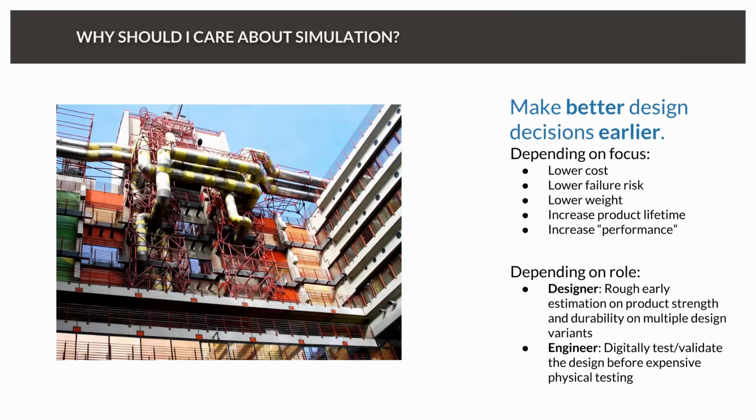Back then there was no computer or CAD technology which helped the engineers and architects to design the building. So everything was based on rule of thumb. And in the end they finished this hospital building, and after some weeks they found out that something was completely wrong with the HVAC system because it was much too hot inside the building. It turned out that the whole HVAC ducting system was under-designed, so all the ductings were too small.